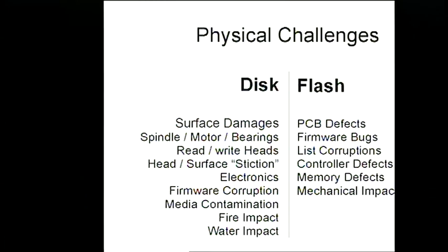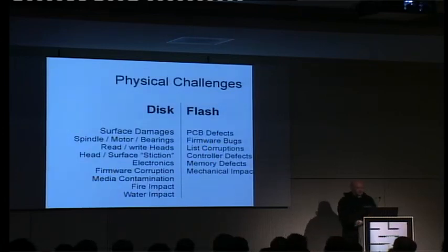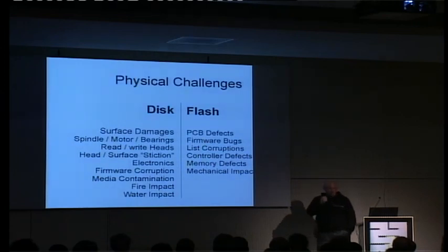And if the heads have not been parked in the designated parking zone, or they have not been moved to the ramps, some of the drives park the heads in an area where they use CO2 lasers to avoid stiction. So they punch little craters in the inner media zone so that the heads cannot stick to the surface.